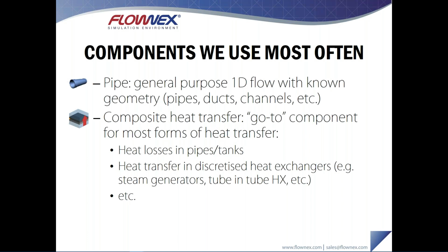For our heat transfer applications, the composite heat transfer component is almost always my go-to component. It has features that can model just about any form of heat transfer. So if you're modeling, say, heat losses in pipes or tanks, or maybe you're trying to do a more sophisticated heat transfer model where you're modeling a heat exchanger that's been discretized, perhaps it's a steam generator for a power station or a tube-and-tube heat exchanger. All of this can be modeled using the composite heat transfer component.